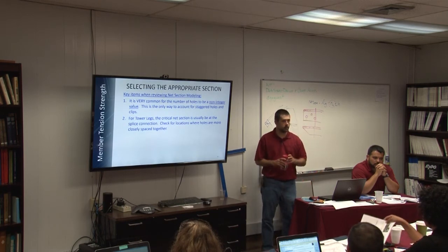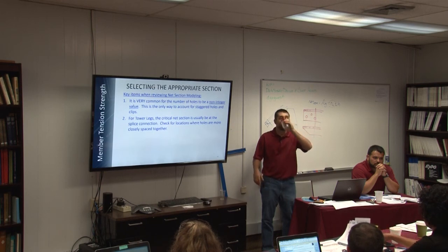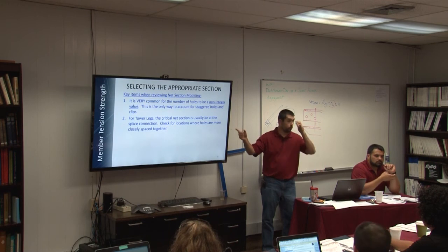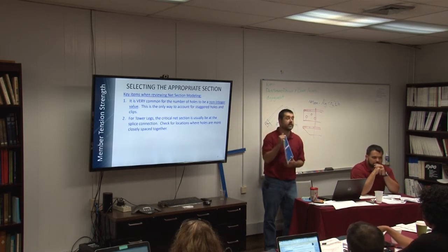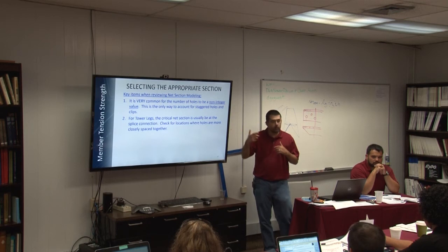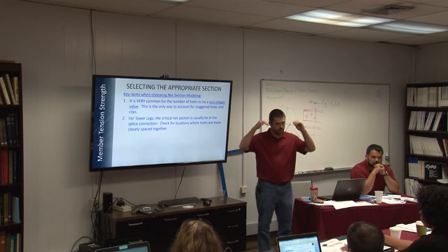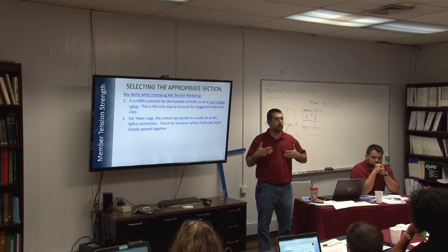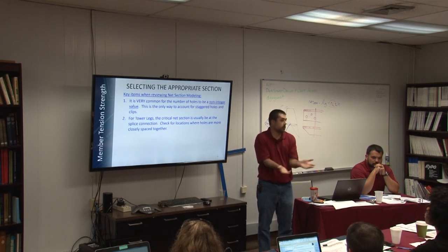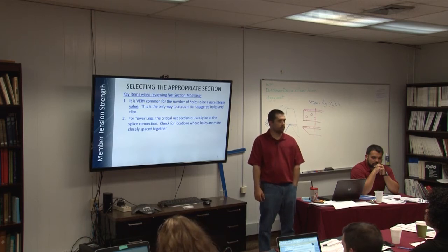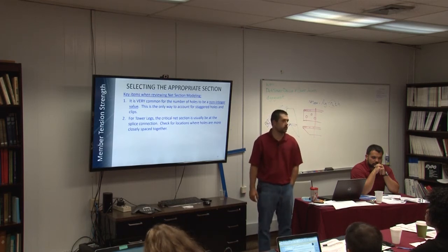I think it's unfair to look at the older structures. I think they are supposed to abide by today's. At the end of this whole presentation, we'll address that, and like I said, the people that put this document out recognize that too, and so they say you don't have to do this. But the other way to think about it is that the standards in here are best practice, best knowledge today on how to calculate these capacities. When we get to the rupture limit states, these are things they didn't look at 40, 50 years ago. But there are recognized ways that fail these members. If you do show that you're under strength because of that, the decision is, are you willing to live with that risk? Because the capacity is a real thing, even though it wasn't necessarily considered 40 years ago.